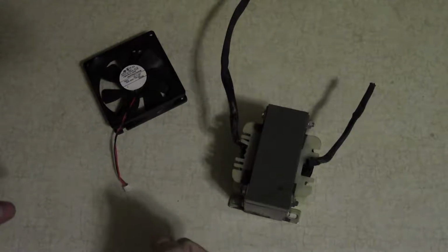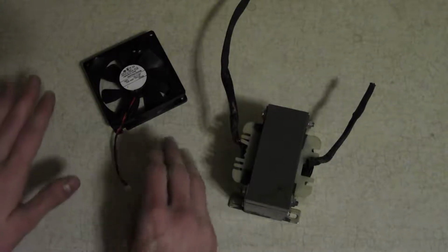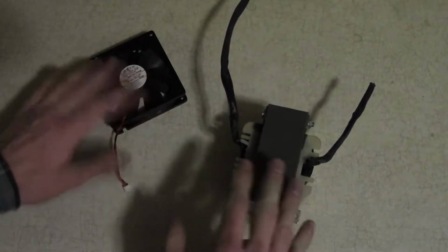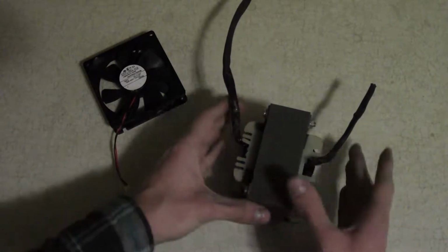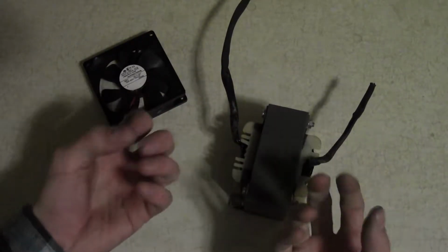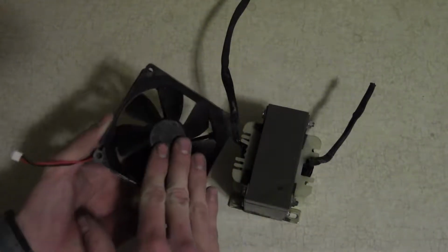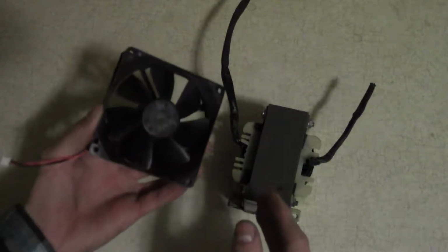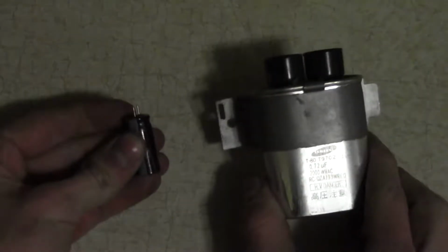Technically, almost everything is an inductive load, almost everything is an inductor. As far as you're concerned, if it doesn't have a coil of wire around some form of substantial iron or ferrite or something like that, it's not an inductor. It has to have a massive inductance, a massive magnetic storage capacity, in order for it to really matter. If it's a small inductance, you don't care. So this motor would have to be much larger for you to actually be concerned about its power factor. The third and final form of load is much less obvious, a capacitive load, and we will come back to this and you will understand this.